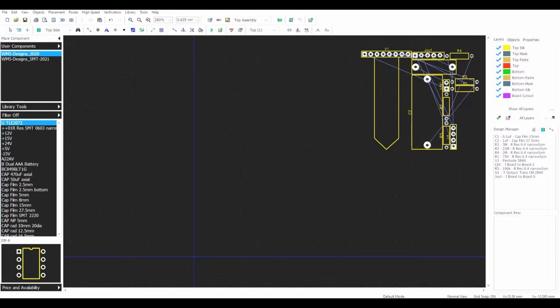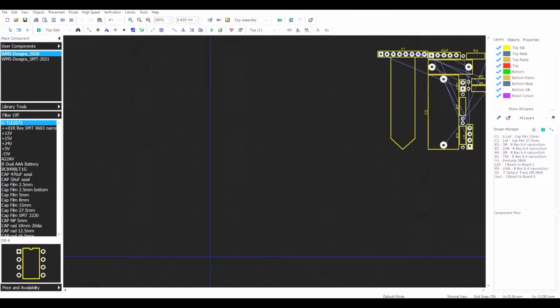So right now what's important is that I know the size of the circuit board I want to use. In this case, this is for a microphone, so the sizing is really critical. I have to make sure it fits inside the microphone. So I'm going to start off with that. This lets me draw the board outline. And what I usually do is just roughly draw it, not really worrying. The last place I click, I don't want to move my mouse again. I click it and then I just hit enter. And then that purple outline is my board.